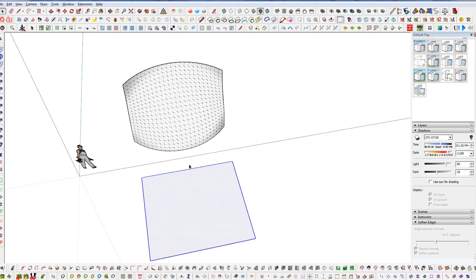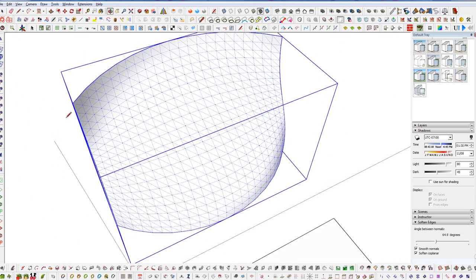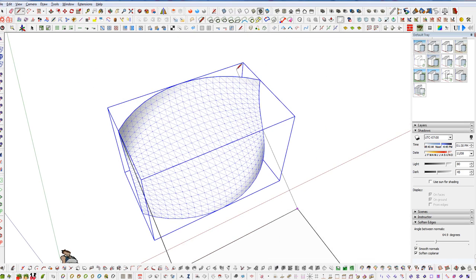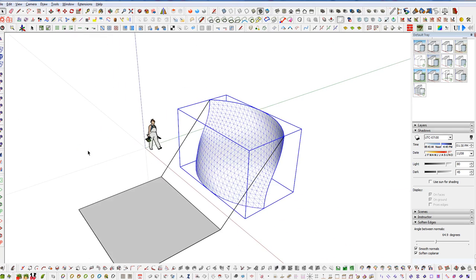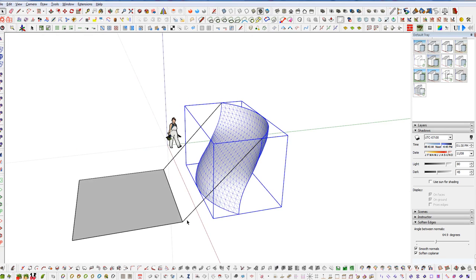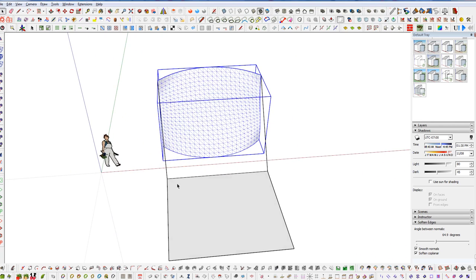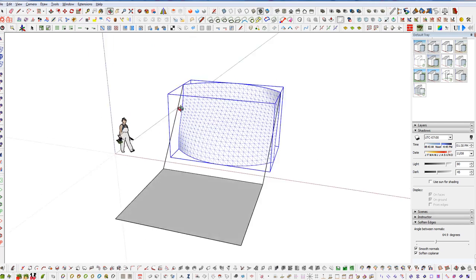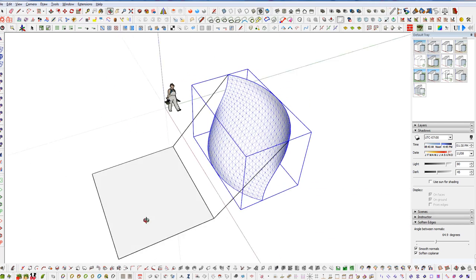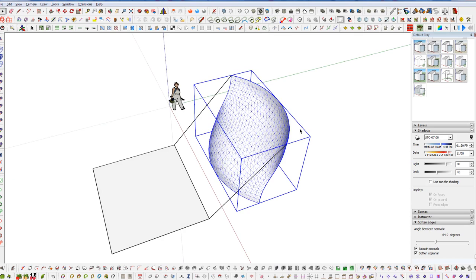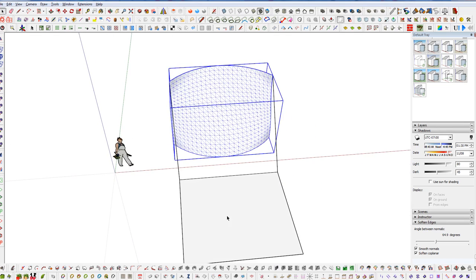So we want to make sure that our reference surface is a group and our target surface is a group, and now we need to create some edges which will connect the target and the reference. So we're going to connect the corners that we want to represent. Essentially, if we would pull this up, saying this is the top, the reference here, this is the top left, and this is the top right, and on the target this is the top left and the top right. So if we would attach, let's say, from here to here, from here to here, then this would essentially be this mesh turned 90 degrees, if that makes sense.